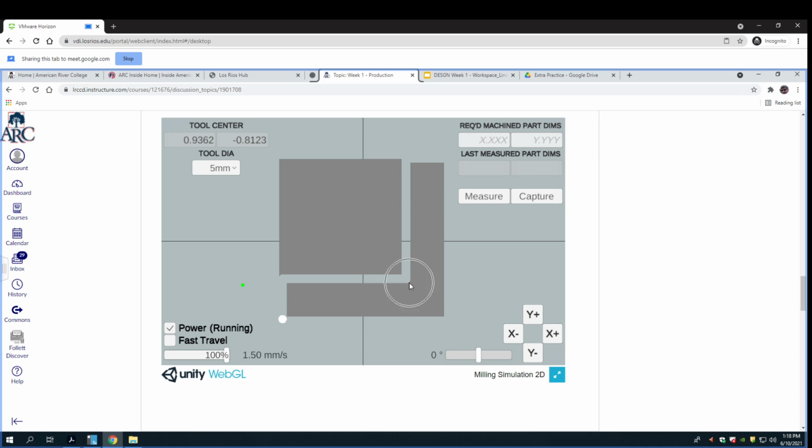Kind of important. It's called a fillet. And your fillet radius is actually important. If you could imagine if this was a piece that was supposed to fit up against this side and then fit against this side, it wouldn't go because this little corner would run into that. And so fillet radii of mating parts have to be designed.